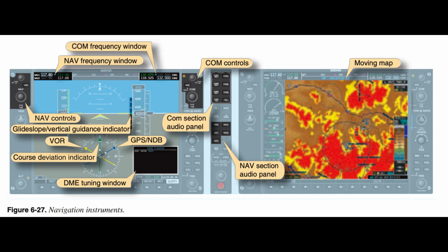Trim. Another important step in attitude instrument flying is trimming the aircraft. Trim is utilized to eliminate the need to apply force to the control yoke in order to maintain the desired attitude. When the aircraft is trimmed appropriately, the pilot is able to relax pressure on the control yoke and momentarily divert attention to another task at hand without deviating from the desired attitude. Trimming the aircraft is very important, and poor trim is one of the most common errors instructors note in instrument students.